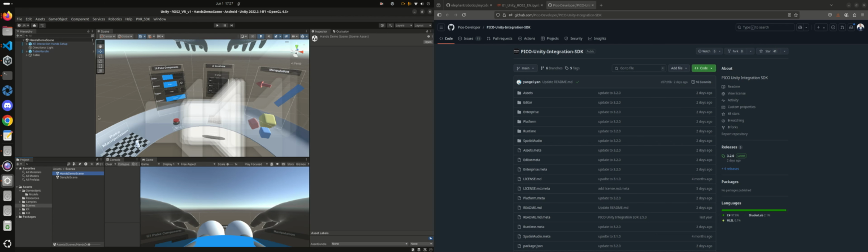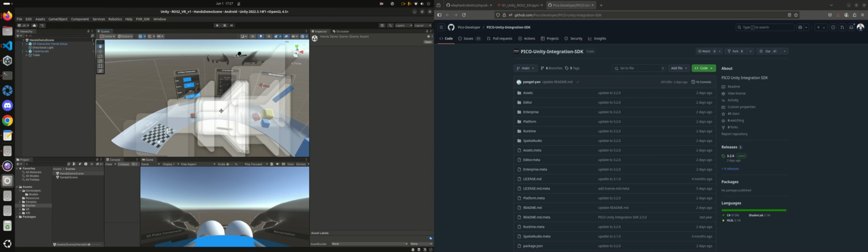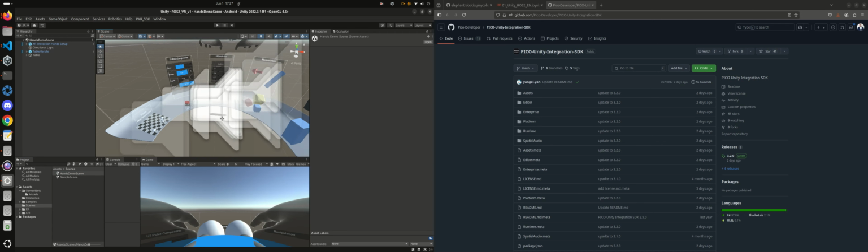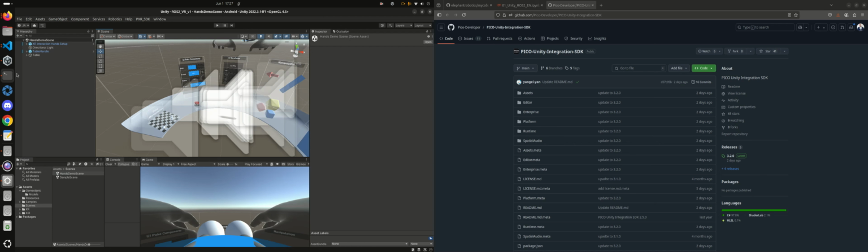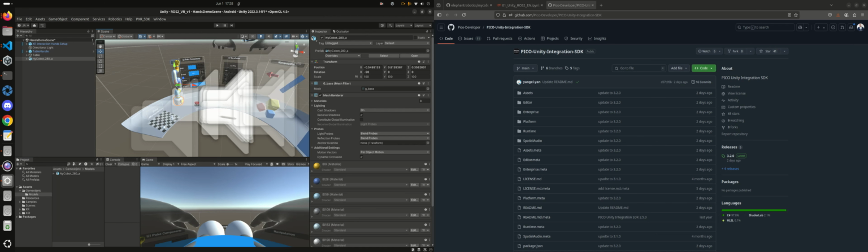This is our scene, and now we start to modify this scene, maybe adding a new object, in this case a new game object, that in our case is our robot. Okay, so now go to the folder game objects, and then to the subfolder models, and then drag and drop the robot into the table.